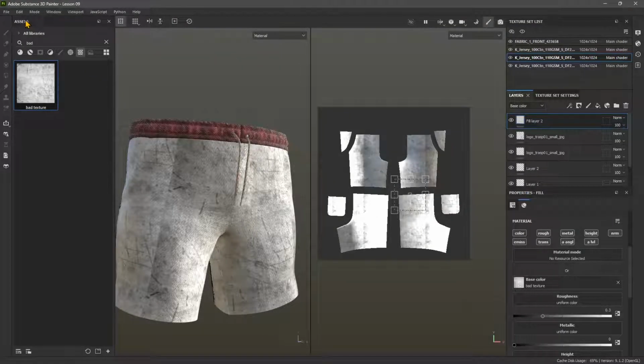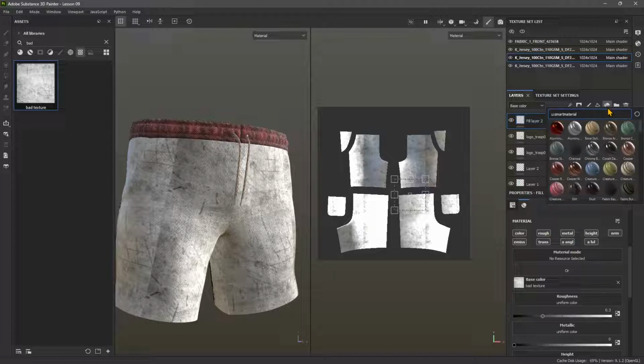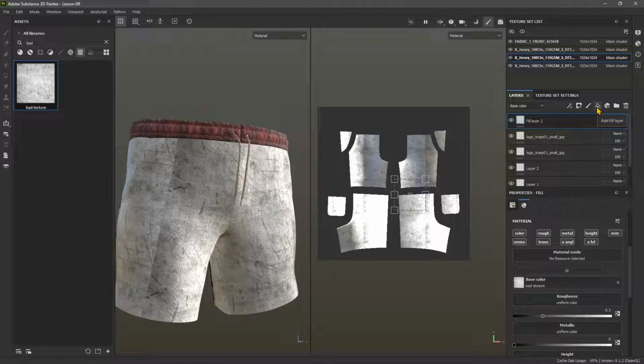Now I just realized I was in Italian language, so I switched quickly to English. And to use the clone stamp tool, we need to add another layer. Now, we have different operations we can do with layers. We're gonna discover more in this video. So you can create groups, you can apply a preset directly from here. You can use the fill layer, as we know, and the brush layer here, or the standard layer that we use so far. And then you have masks, which we're gonna talk about later. And then you have this other one here, which is gonna add more effects. And so we're gonna see what generators are, and what, for example, a levels adjustment layer is.